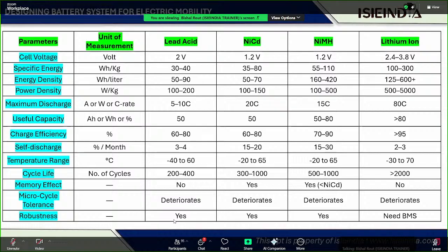And again, the lithium ion battery has better electrode kinetics than the lead acid battery, and it has a lower voltage drop, basically, and higher conductivity. That is the reason a lithium ion can discharge at an 80C rate, whereas lead acid cannot discharge at that rate. So this is all about the C rate.